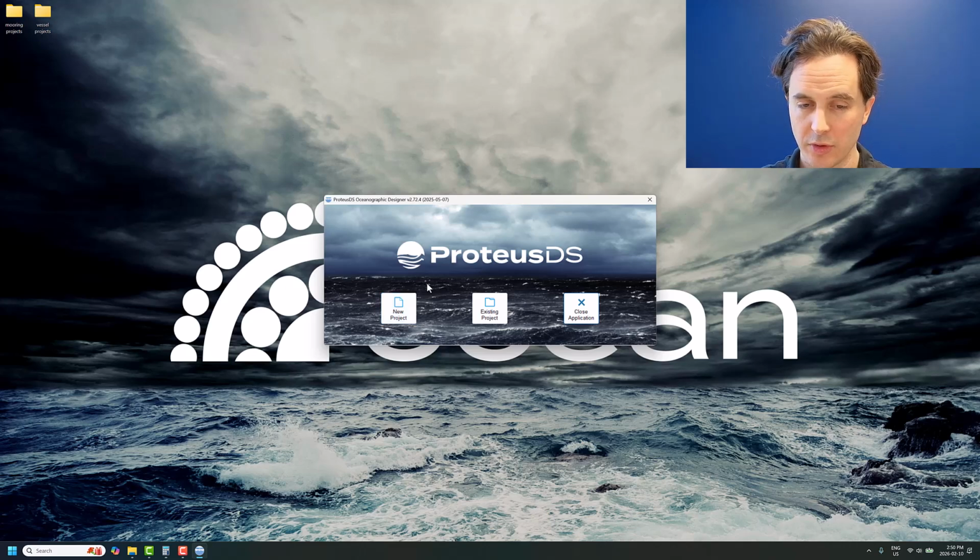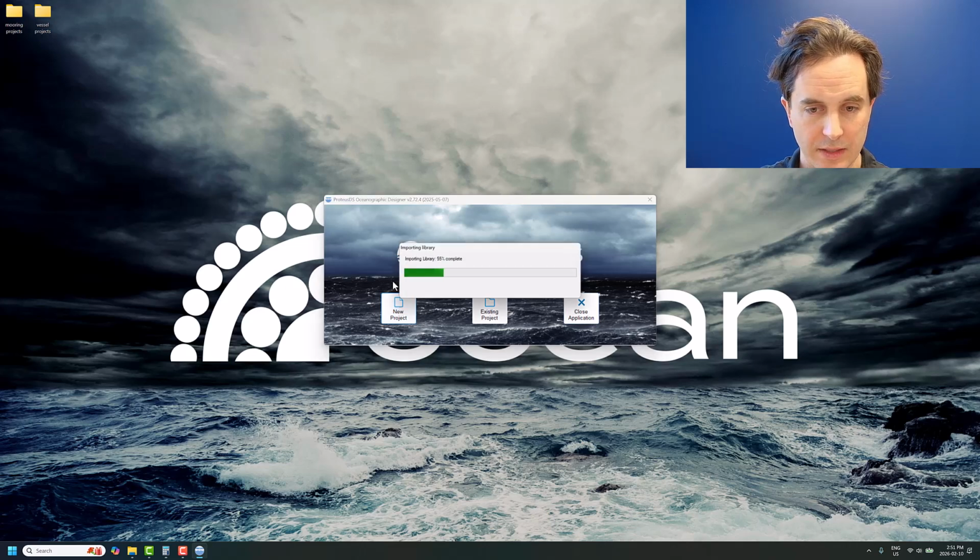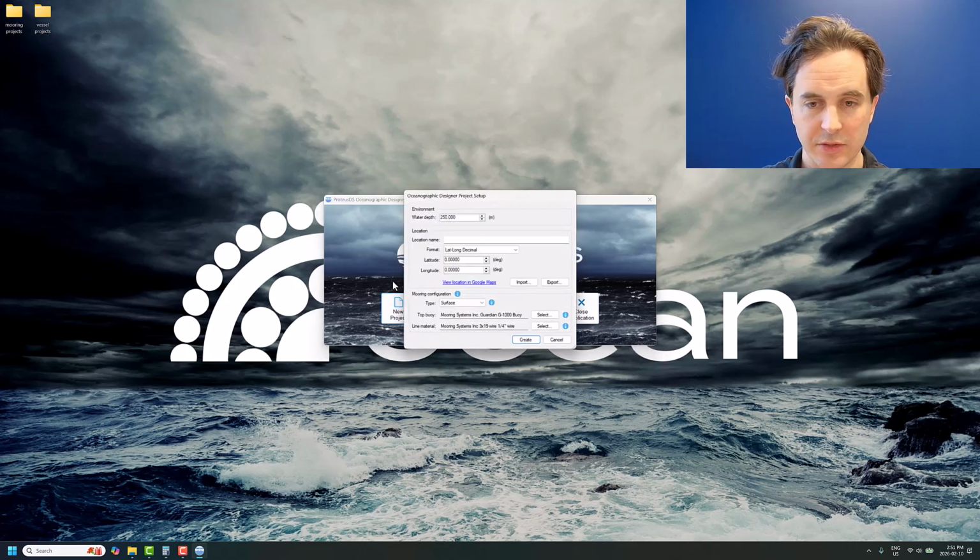You could set up moorings like this with Oceanographic Designer. And certainly that's fine if you're mainly interested in exploring the driving dynamics in the mooring and the loads, the maximal loads and waves and currents and things like that, and mooring deflection. But in some cases, particularly with shallow water moorings, it's quite fast to set everything up in Simulation Toolbox directly along with a rigid body buoy model.